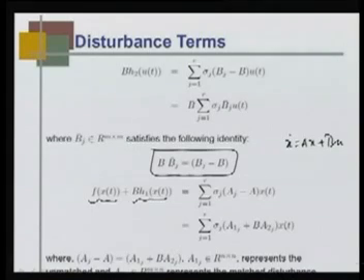So, anything with b we can say is an excitation, because anything multiplied with b is a kind of excitation to the system, and this term is not. It is not multiplied with b, it is a separate term, the unmatched disturbance, and this is the matched disturbance, meaning this is an external excitation, a disturbance excitation that is exciting the system, because we say b is the control matrix. In that sense, this one, a 1 j, is the unmatched disturbance, and this is the matched disturbance.